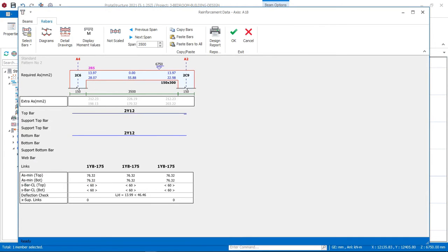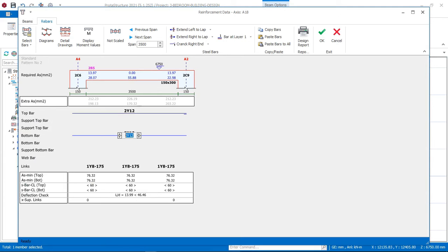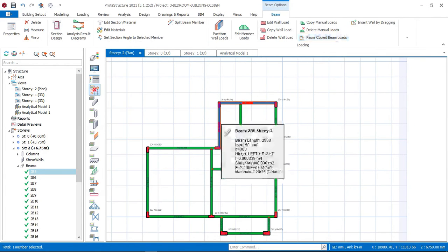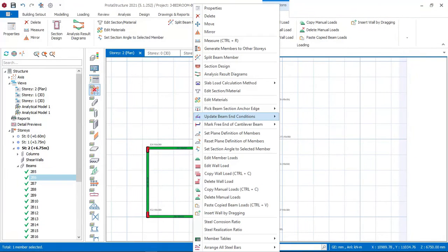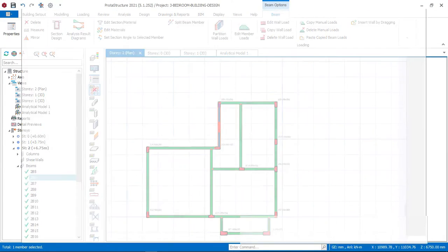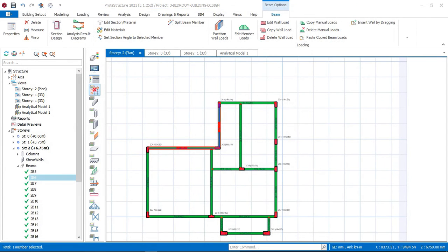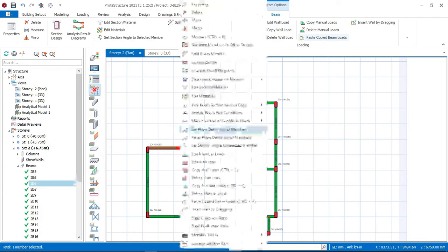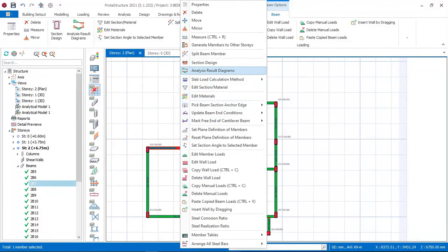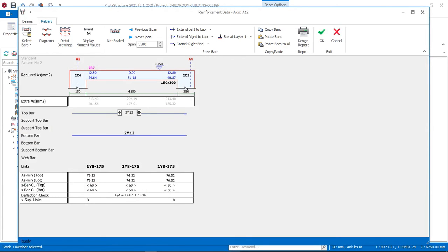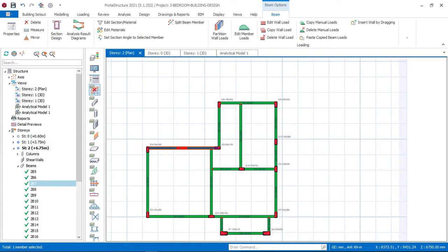I always advise my subscribers that you should spend time to check all your steels, all your reinforcement that the software used to pass your building members or your structural members for you. Else, if you just go ahead and you didn't spend time and go ahead and export all your details out, you are going to be having issues for either oversize of reinforcement, or the kind of connections you'll be having will not be okay.